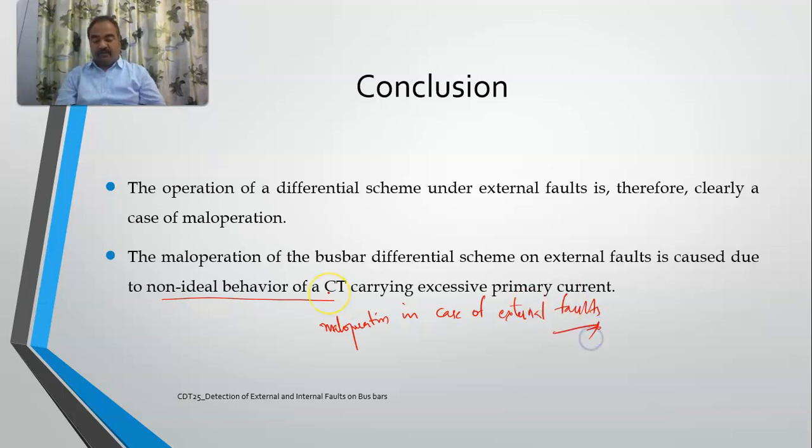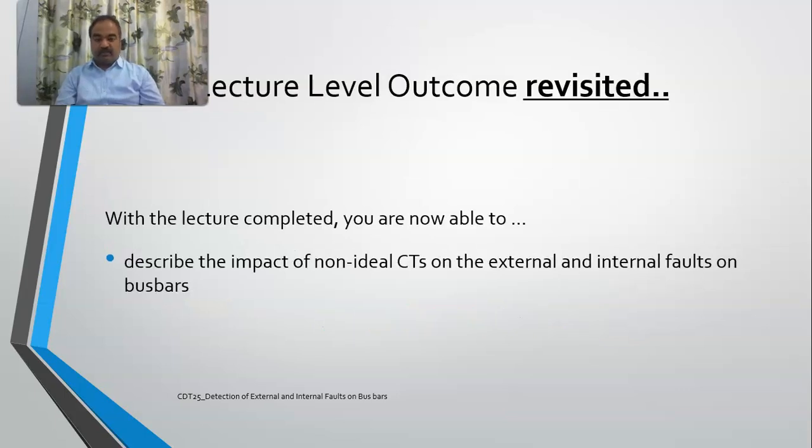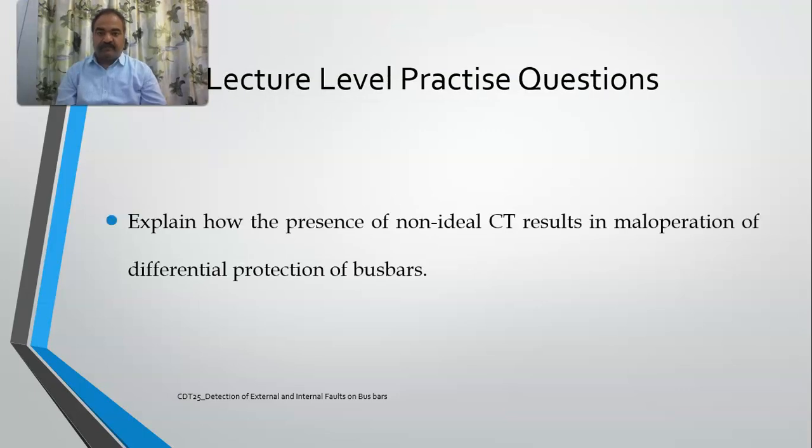So what should we do whenever we are erecting the CTs? We should take care of whether it is saturated or not. Okay. So I hope that now you have understood the significance of saturated CTs on the external and internal faults of the busbar. Okay. So in the next class, we will see how to represent a saturated CT for our analysis. Thank you.